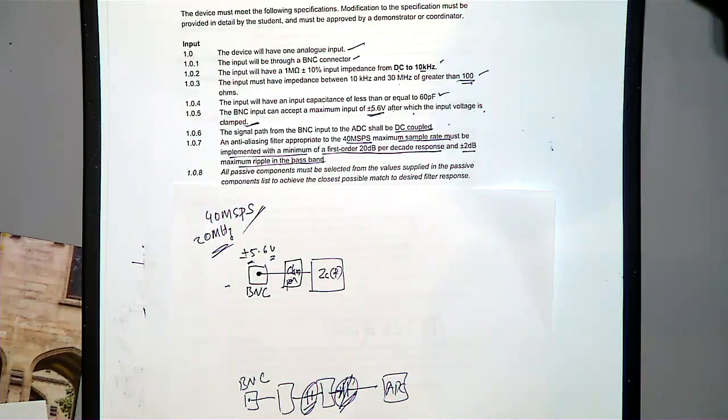As a system engineer, you know that one. In the same way, when you have an ADC, people always put a low pass filter, and I will tell you why. We will study the anti-aliasing filter, especially for the DSO. Even for other applications, people put one, because when you have 40 mega samples per second, as per the Nyquist theorem, your bandwidth is around 20 megahertz, half. We need to stop all the frequencies above that, otherwise you will get an error. So whenever you have an ADC, you need a low pass filter. These are the things you should remember as a system engineer.